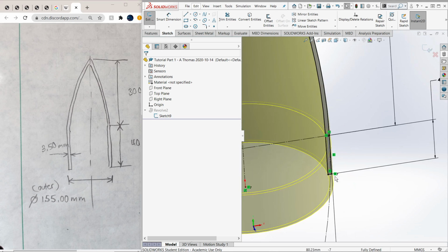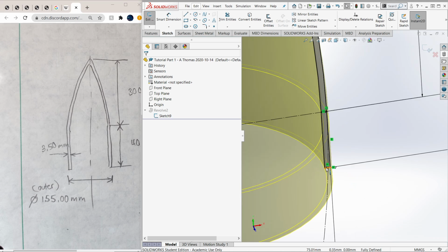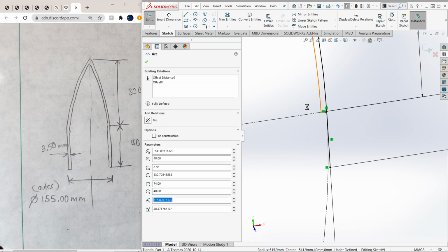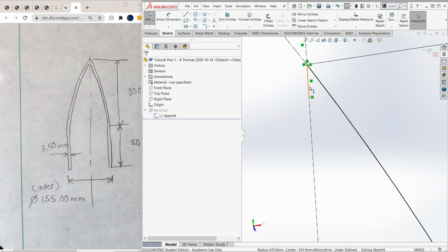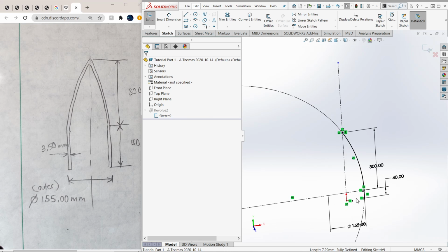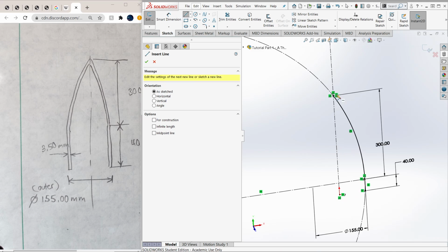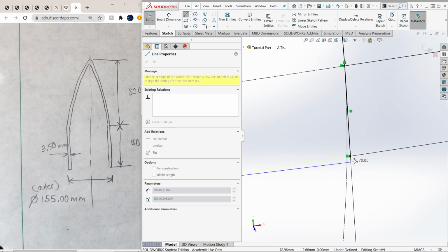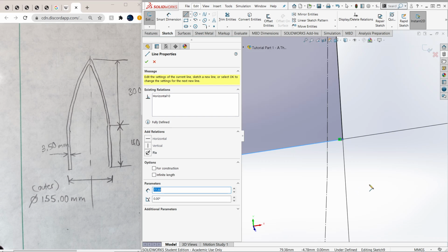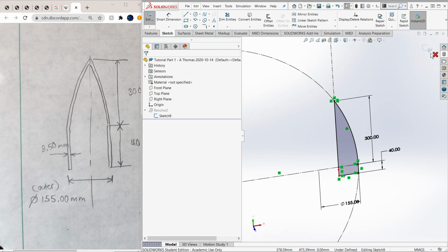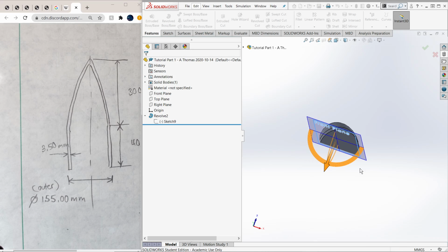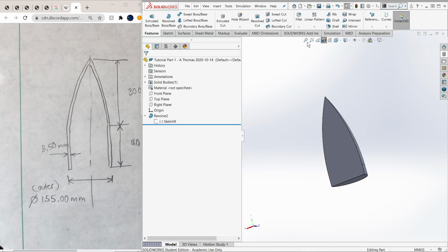I'm actually going to get rid of those internal lines, that bottom one, that shoulder, this and that line, and I'm going to make a solid nose cone. So I'm going to go from this top point to here, to here, to, I'm going to zoom in so I click the right thing, to there, hit escape. So I'm going to revolve this solid nose cone, right? So it's solid. If I take a look at its cross section, it's just a solid nose cone.